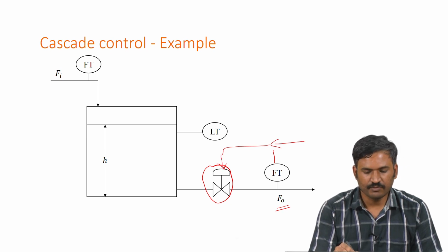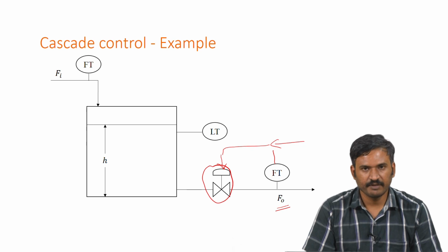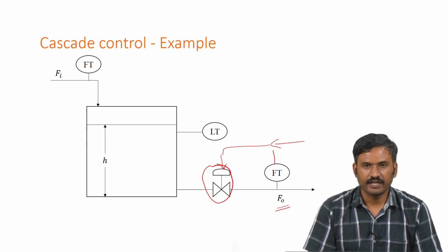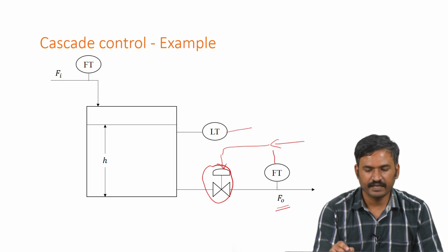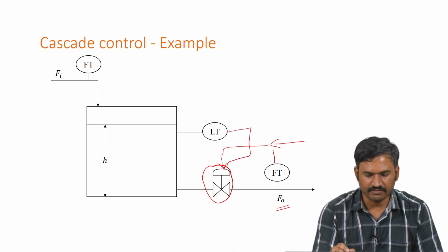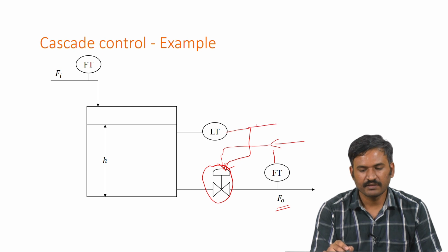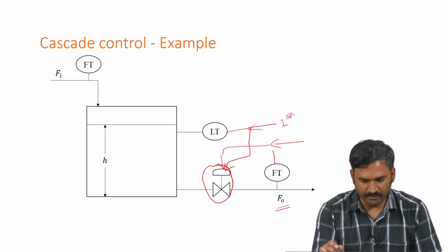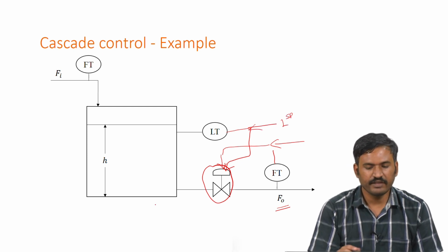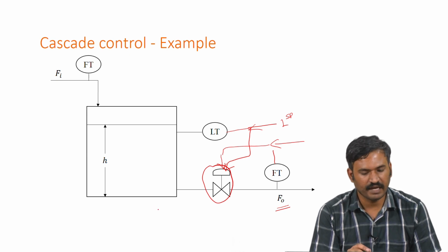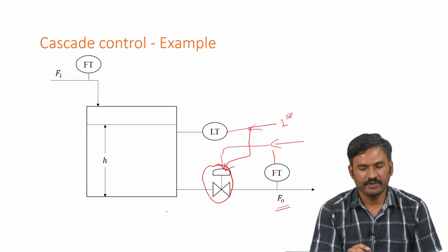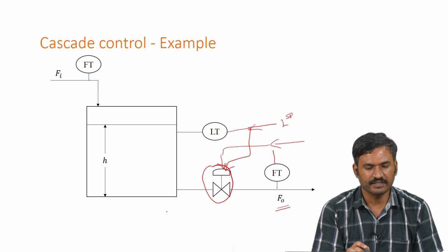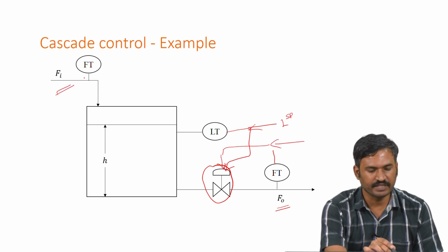Now, this is how most of the traditional control will be done, or we can do it another way where the level transmitter can directly control this valve using a set point to level measurement. Now, if the tank is large and it has higher volume capacity, then any change in level will be very small with respect to the inlet flow change.